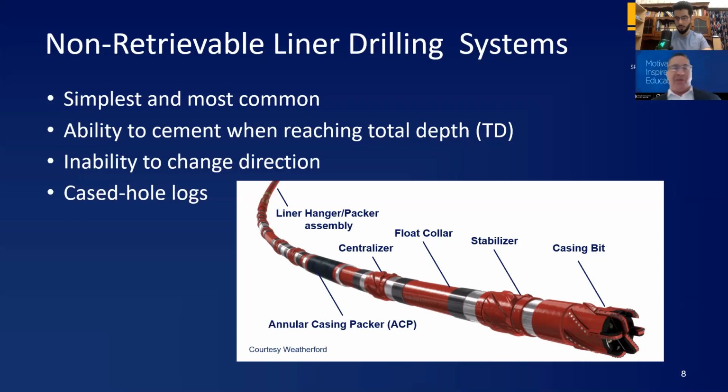So remember that. The reason is we don't have as high pump rates when we drill with liners, or for that matter casing, because like I said at the beginning, you have a narrower annulus. So per unit pump rate with liner drilling, you get a higher annular velocity versus that of a conventional casing installation. And with that higher annular velocity, you get better hole cleaning, albeit at lower pump rates than you would with a conventional installation because of your narrower hole geometry. Sleep on that and ask me if you have any questions. That's a mouthful, but it is a fact.